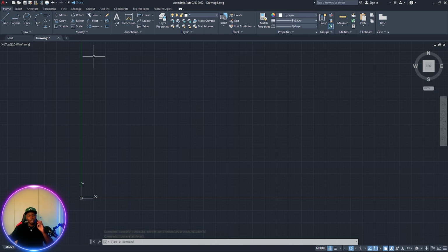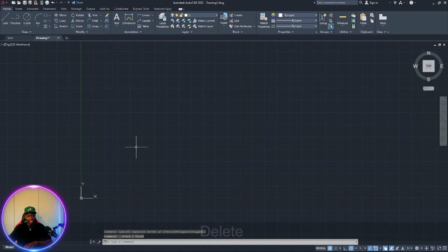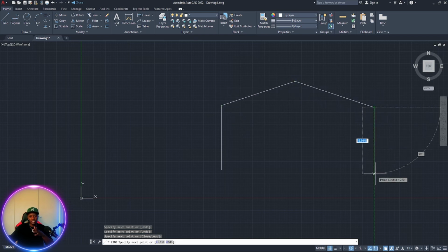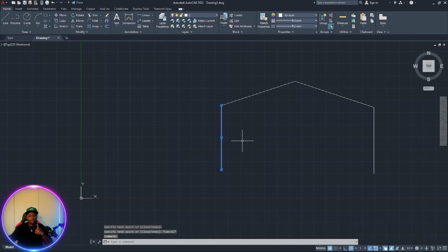And I'm gonna show you the difference between using a line and the actual tool for a rectangle, or using a polyline instead of the other shapes. So let's go to polyline. Polylines and lines are different in one thing. If you take a line, you click it from start to end, you go to the other side, and the other side, you press escape. Every stop makes a line on itself, but it's joined.